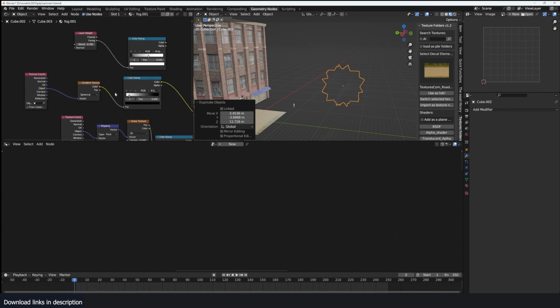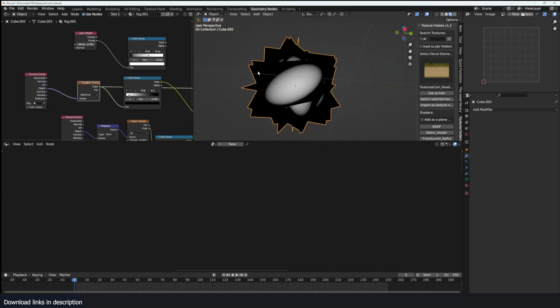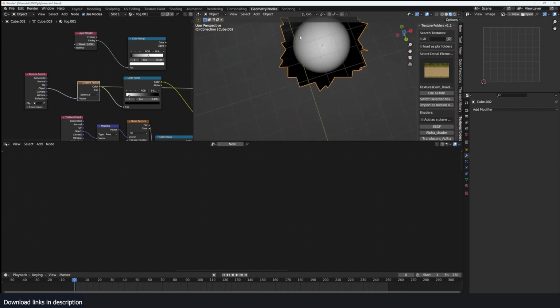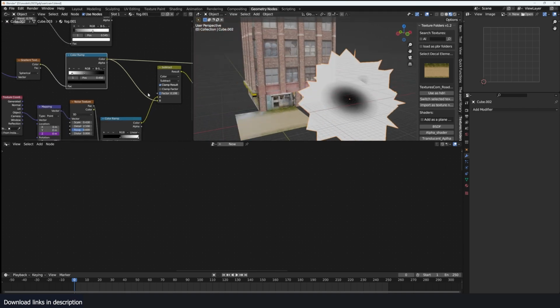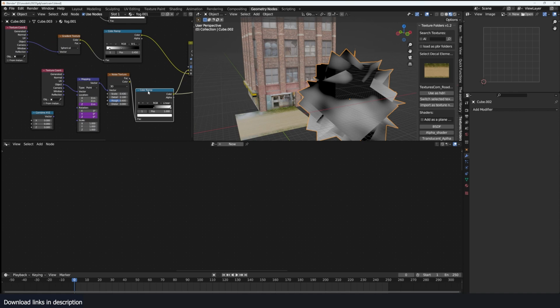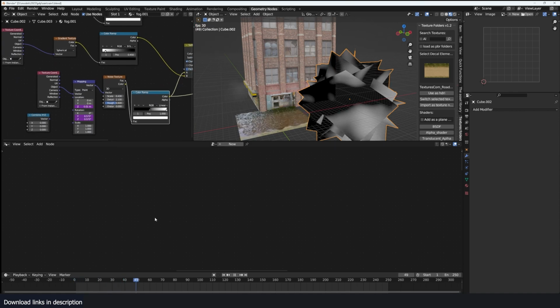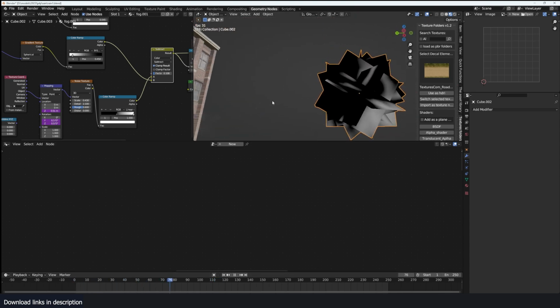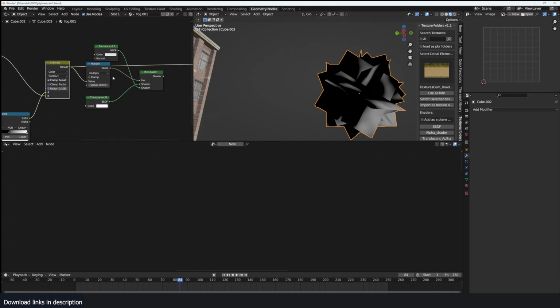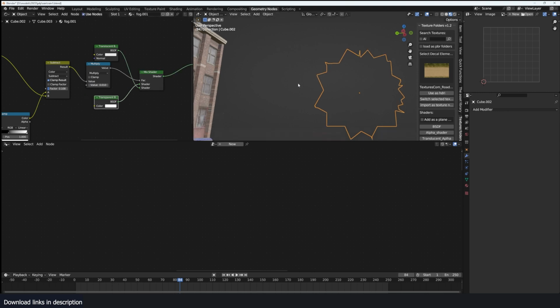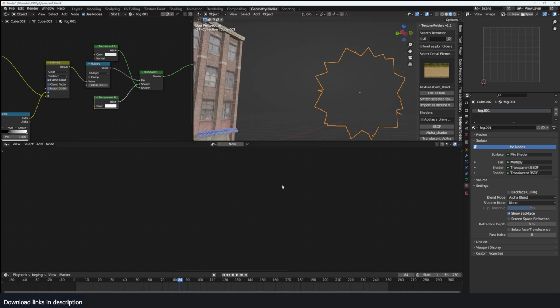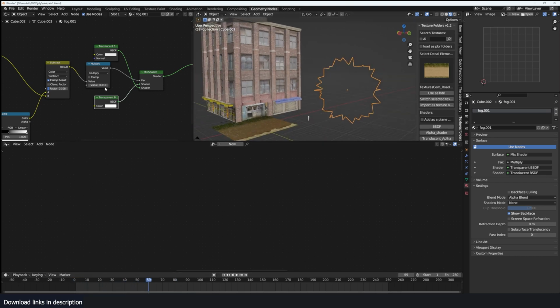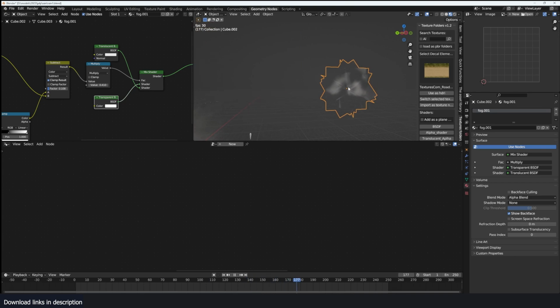The way I made this material is I used a gradient, a texture gradient, so that in every direction you look at it, it's going to be like a circle, like that. And I inverted the circle, used some light noise, and this noise is animated a bit. So to add that animation, you see, and subtract that from our gradient, and you get a noise effect like that. And then use a translucent and transparency material, and make sure you have alpha blend on, so you get a subtle look. And I can amplify the effect so that you can see what is going on. Yeah, so it's basically some fog effect animation happening like that.